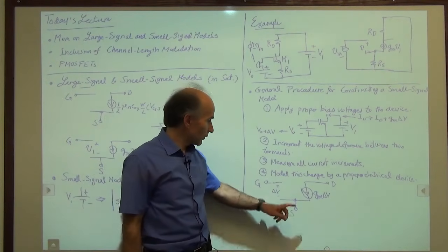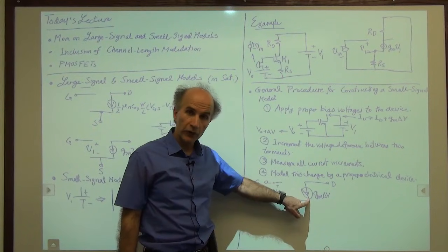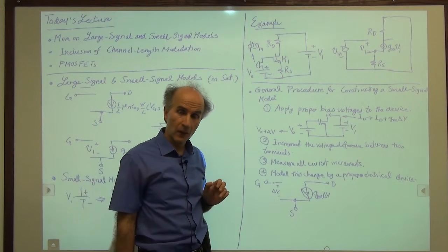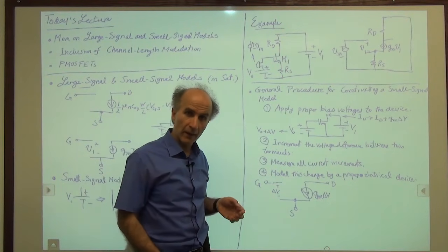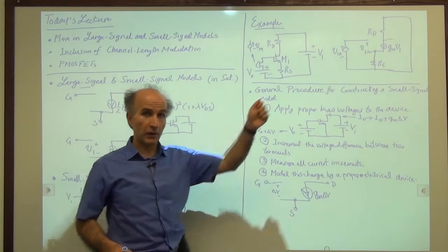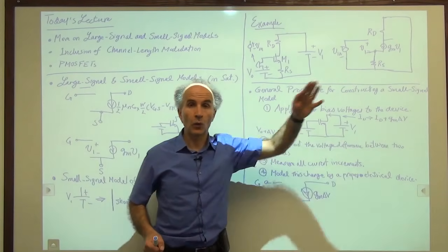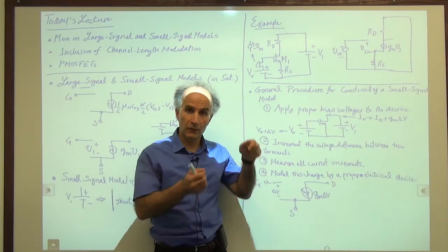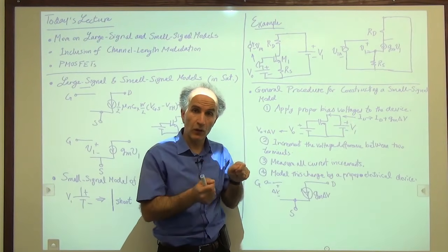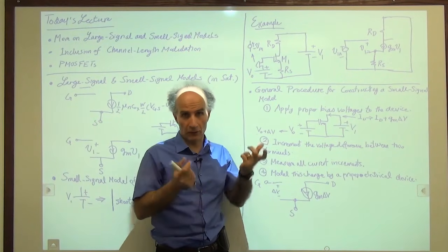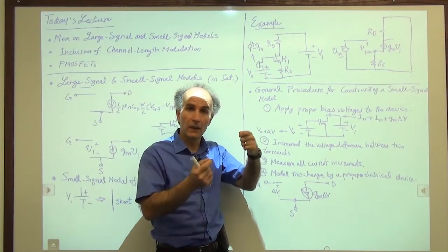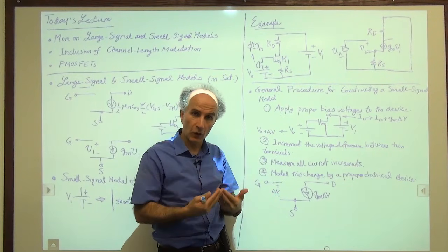All right. Why should this be a voltage-dependent current source? Can it be a resistor? No, because the problem is that we are applying a voltage change over here between two terminals, and we are measuring a current way out here. The only time we can use a resistor is if the voltage and the current belong to a two-terminal device, like a resistor, where you apply voltage across it, you measure current through it, and those two are related by Ohm's law.